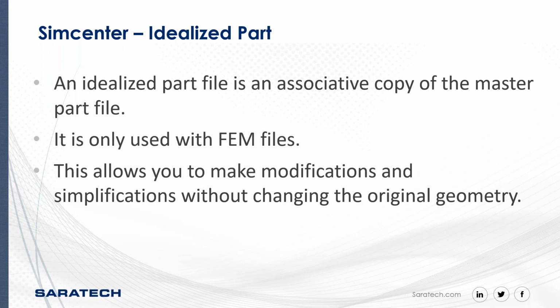The idealized part is an associative copy of the part file, and this is only used with the FEM. So what it does is it takes an associative copy of your CAD part and allows you to make modifications to it without modifying the original CAD geometry.